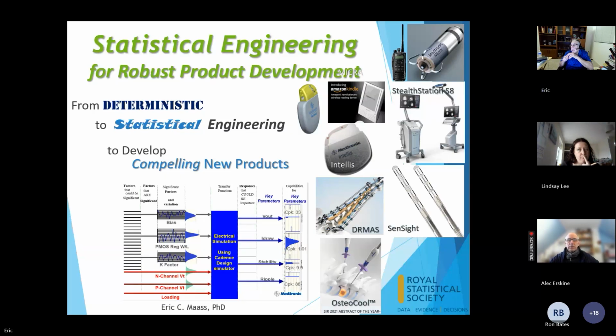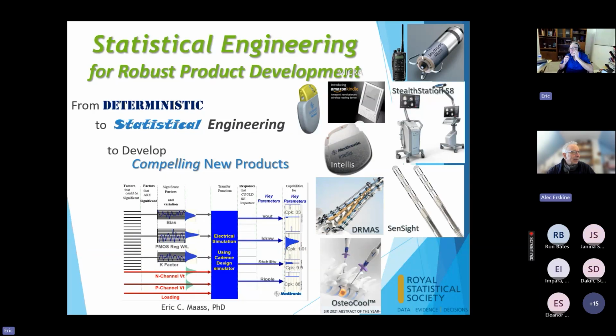Eric, that's all very interesting. As I understand it, you're doing the Monte Carlo off a model rather than off actual experiments on the piece of kit. The model might be a regression or something like that, but did you make allowance for the fact that the regression isn't an exact replica of reality, and did that come into the variance that actually goes into the calculation of your Cpk? Cp and Cpk, the capability.